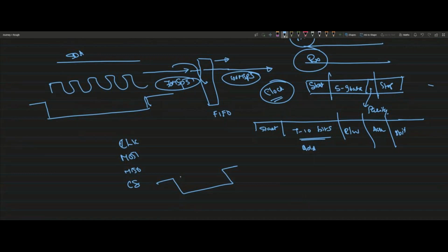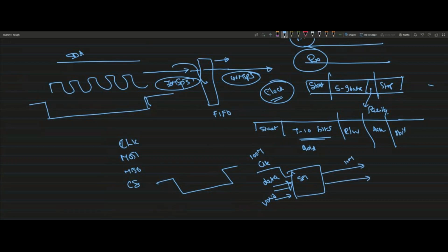Yeah. That SPI circuit you are designing, right? So whenever I say SPI, this is the RTL Verilog code that you are writing in the FPGA. For example, this is the SPI Verilog block. The inputs to this are maybe the 8-bit data that you want to transmit, a valid signal, and some reference clock. If it is 100 MHz here and you want to send at 10 MHz, you might have some clock divider circuitry here, and you will be pushing data bit by bit through master out slave in. You will be designing that. So the clock you are generating through a PLL or maybe a counter, or you might be giving the exact clock itself.